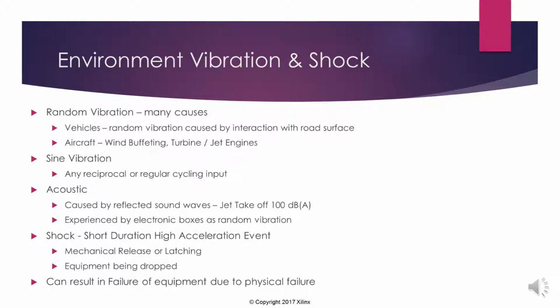But there are other areas where this has occurred. Many years ago, I saw an FPGA that was on a shaker table that was powered. It was going to be powered in launch, so it was powered on the shaker table, and it would keep locking up. The reason it kept locking up while it was on the shaker table was that they'd used a one-hot state machine. We're going to be talking about state machines and how to protect them in a little while.